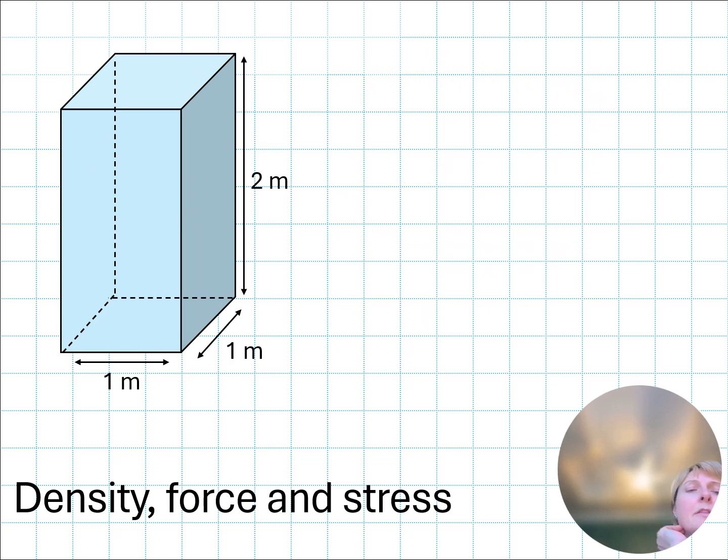Now let's imagine that the volume of mercury is doubled, as shown in this picture, so that my bottom area is still the 1 square meter, but now I have a column height of mercury that's 2 meters high. So my unit weight of the mercury doesn't change. This is a property of the mercury. So my specific weight is still 132,769 newtons per cubic meter.